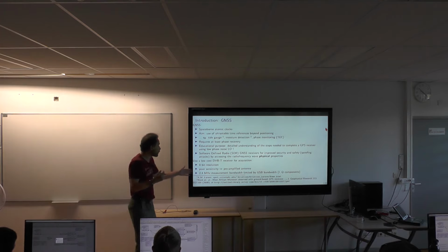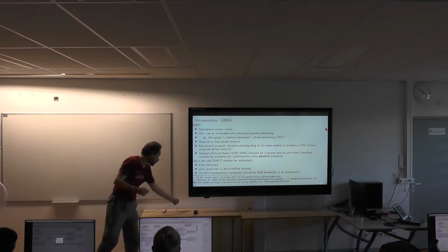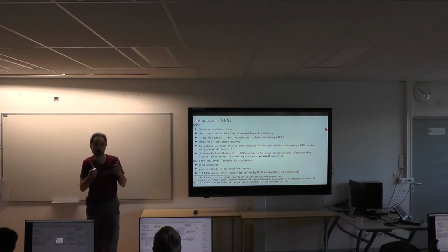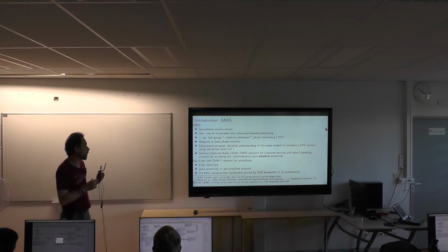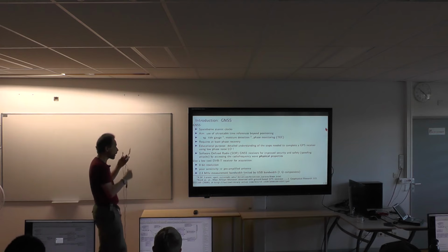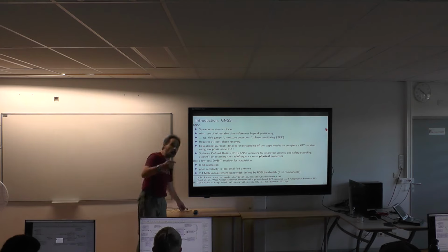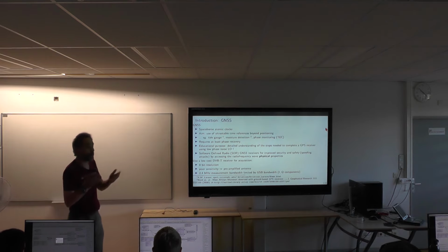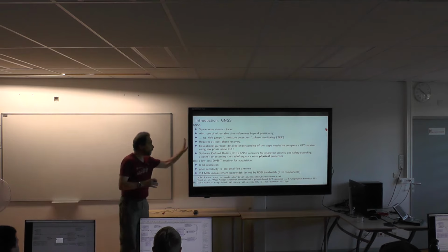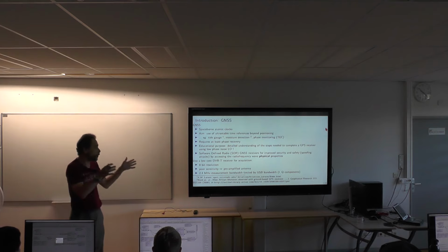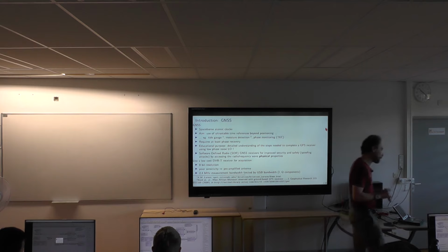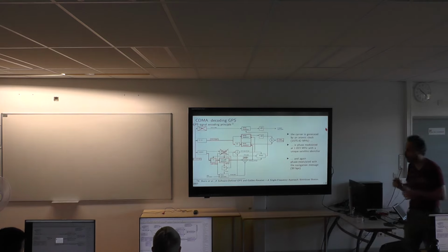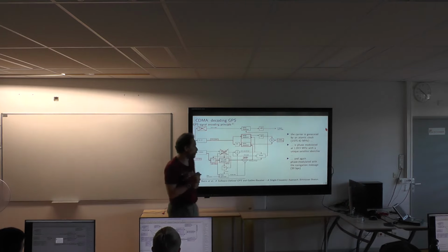And the other limitation is the bandwidth. These receivers have 2.4 megahertz bandwidth on carriers ranging from 20 megahertz up to 1600 megahertz. And because GPS in the L band is at 1.57 gigahertz, that's well within the operating condition of these receivers. But we only have 2.4 megahertz bandwidth, which is enough for the legacy GPS L1 signal, but that would not be enough if you wanted to address the newer signals L5, E5, or Galileo E1. So that's the reason why the title of the presentation is GPS decoding, because we would not have enough bandwidth with these receivers to analyze more advanced GNSS signals, even though everything I'm going to tell you is applicable to these signals if you have a bit more bandwidth with your SDR receiver.